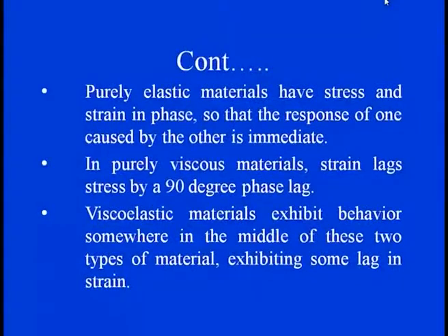So, when we talk about a purely elastic feature, we know that the stress and strain are in the same phase, and the response is quite rapid and linear. In a purely viscous material, the strain is always lagging the stress. Please remember, when the viscous feature is added to the material property, the strain always lags the stress by 90 degrees, with this phase angle.